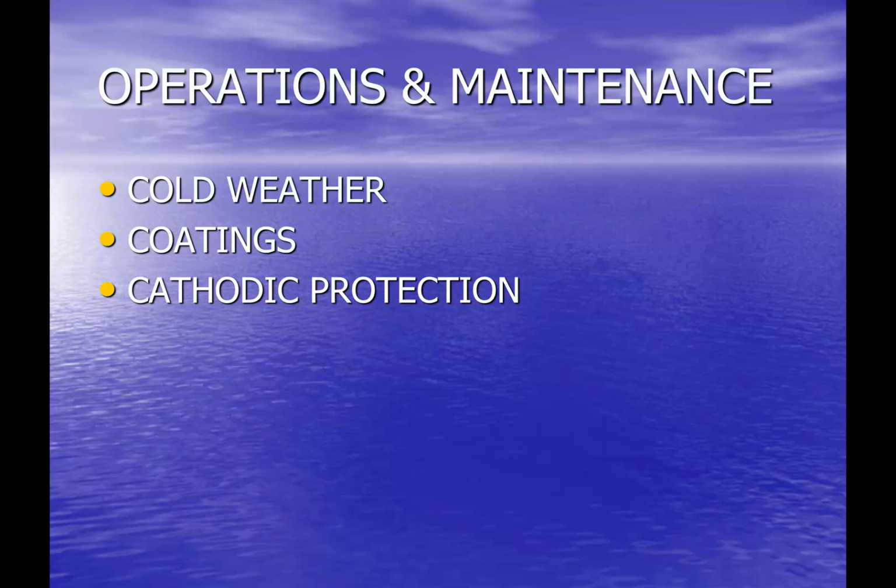The cathodic protection can be a supplement to it, but depending on how you're operating it, we actually had one reservoir where we had a cathodic protection system and a coating, and the operation of the cathodic protection system was actually damaging the coating. Now that's a unique case. I'm not suggesting by any means that it happens everywhere.